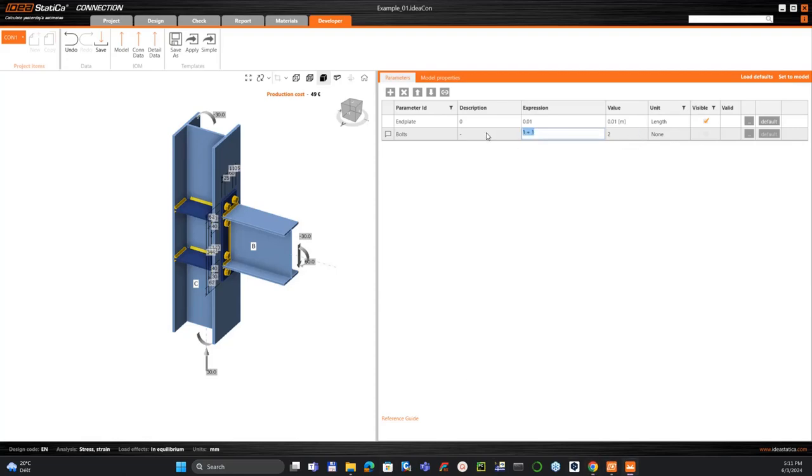You need to use special characters like M12, 8.8, and the comma up. As you can see, this is my string. You need to use it like this. And the value is written here. You would like to also see it as visible here. And right now we need to assign the bolts to the properties of the bolts.